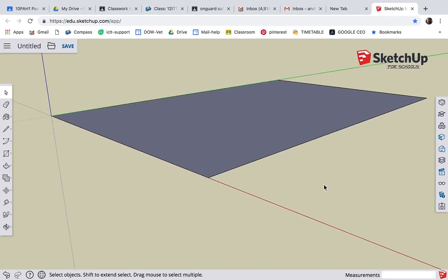So, first of all we're going to draw the side here. We're going to draw a rectangle. We're going to click on that corner there, R for rectangle, click, drag, and we're going to make that 175 by 16. We're going to make it 16 mil thick because the size of this box, if we were to make it 19 mil thick, it would just be a little bit too thick and look too chunky. So we've reduced it to 16. 16 millimeters also allows us later on, if we want to, create some sort of shape on the outside of the box. And again, I'll talk to you about that in class.